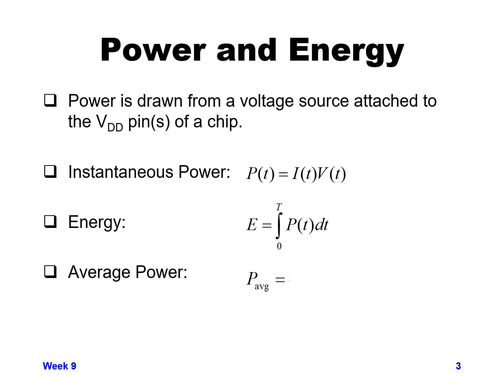And then finally, your average power is taking your total energy over a given time period and dividing by the amount of time that that time period took up. So E over capital T, which of course then if we substitute in the value of E is 1 over capital T times the integral from 0 to time capital T of your power P sub T as a function of time.